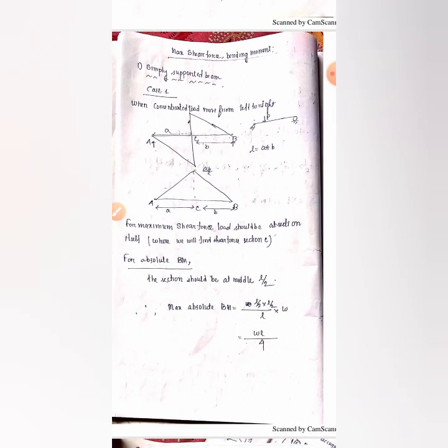Now the most important part of this chapter, and you can say the most important aim of drawing ILD. I discussed earlier that the biggest purpose of drawing ILD is nothing but to find the maximum and minimum shear force and bending moment. Using the ILD concept, we can design our structures so that we can get the moment and the shear force that much we want. That means we can design it up to our requirement. It is the main purpose of drawing ILD.